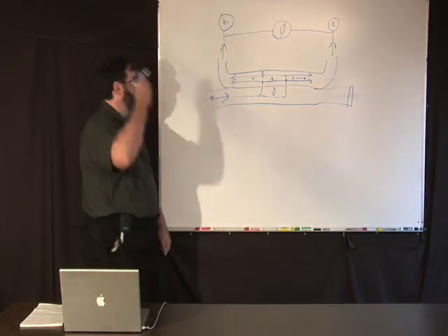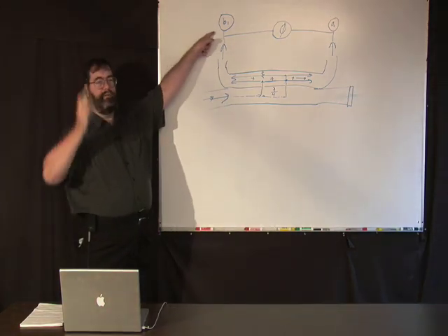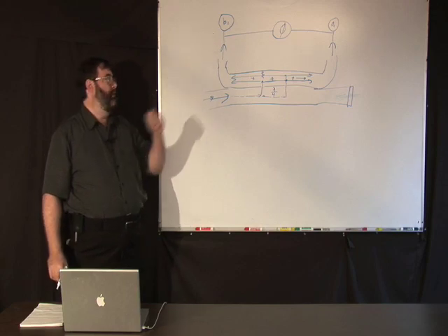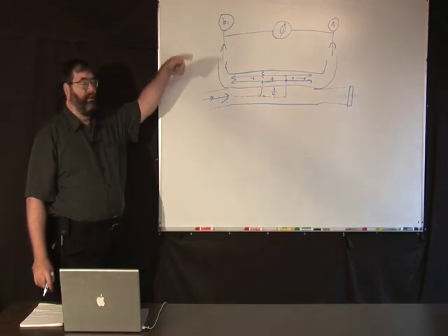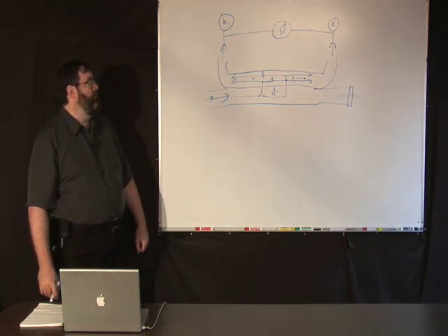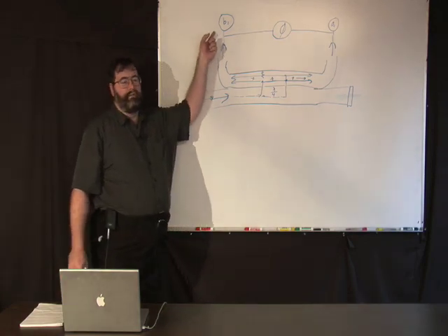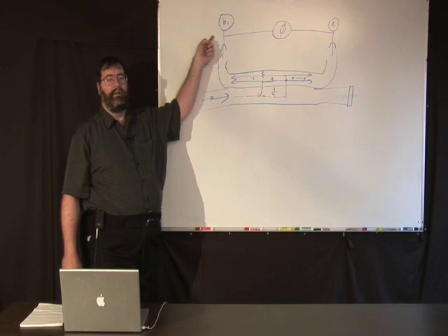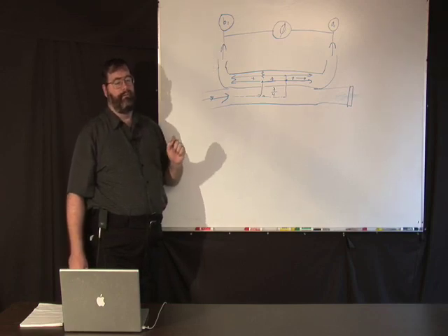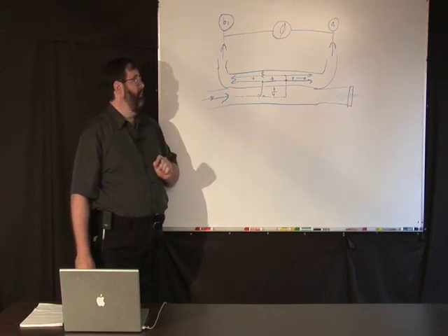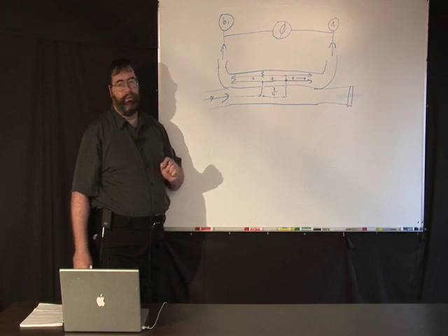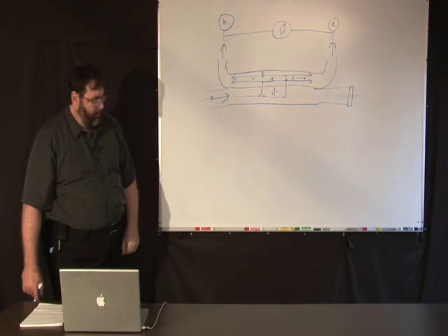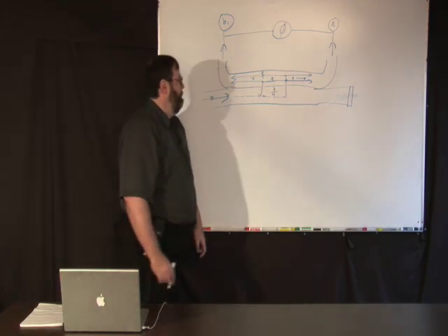Okay. This can be anything. This could be a power measuring device, and you take the square root. So these things have to indicate voltage-like waveforms. So these could be power sensors. They could be anything. The only thing that's really critical is they're linear over the range that you want to make reflection measurements. We're going to talk about how you might calibrate this setup with only knowing that these things are linear and the phase is relatively accurate.